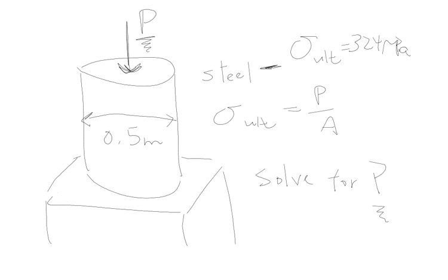So why is this risky? Well, because if you sell this to the customer and you tell them, right, you could apply this much P, and they actually go ahead and apply that much, what are they loading this structure right up to? They're loading it right up to the breaking point, okay? And that would be fine if you are absolutely certain that the steel that you've used is fine.